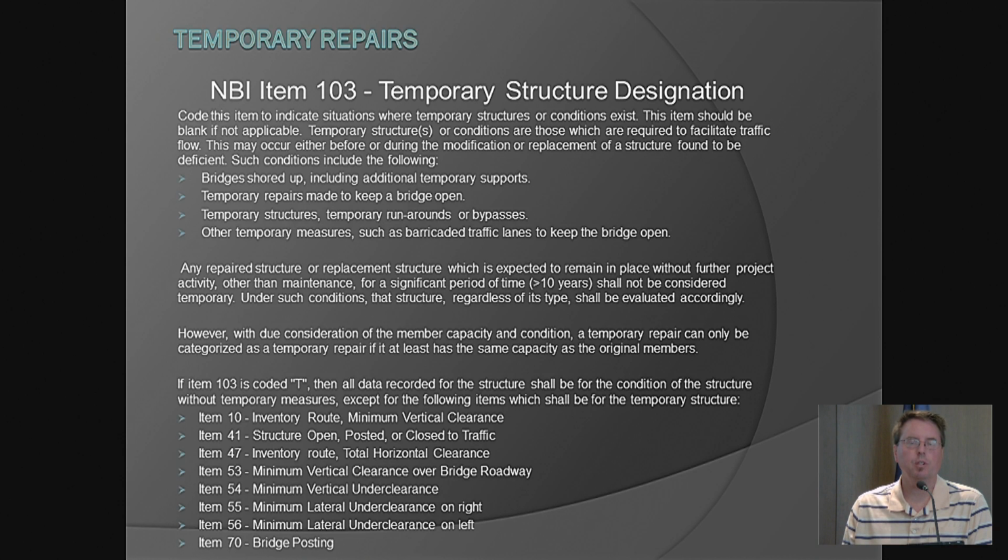The main reason we stress that is that once you put in what you consider a permanent repair, if the old member is left there and it's still in the same condition that it was in, your bridge is still going to be rated down because it is assumed that the old member is still part of the structure, is still attracting some sort of load path, and it has a negative effect on your structure.